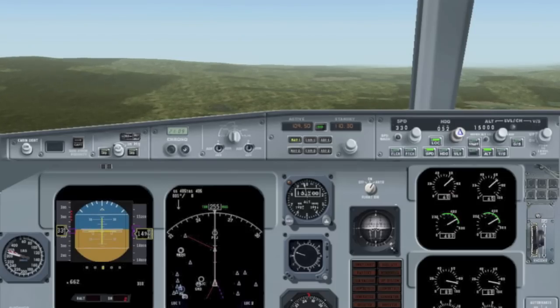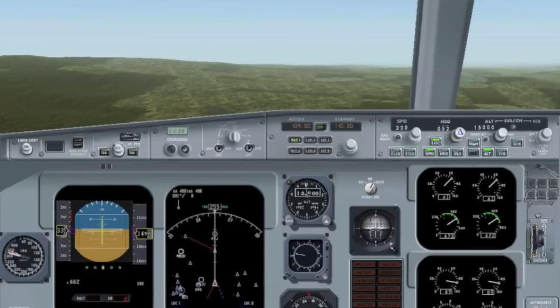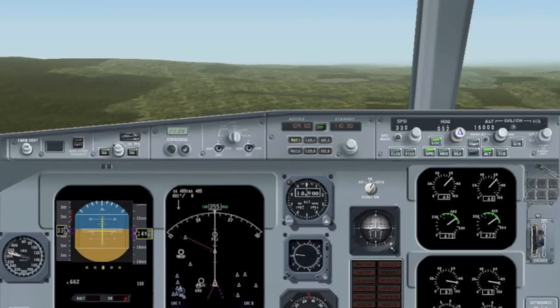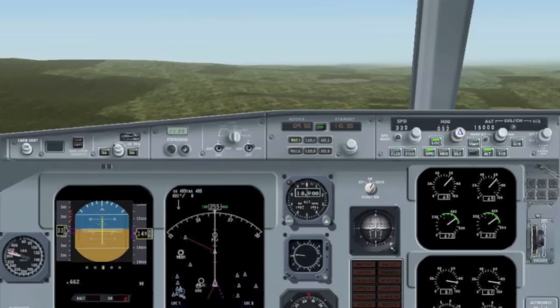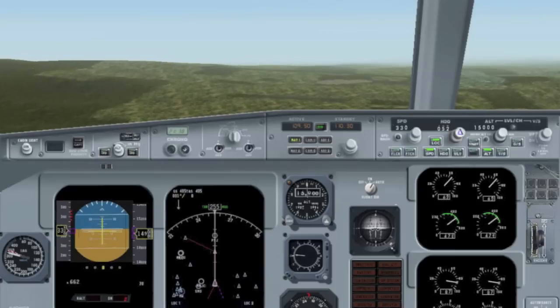Once we have it, we need to enter it into the active screen of our instrumentation, in this case, 109.50, and it is set in the navigation one. Once it is ready, we can wait until we are close to activate it.